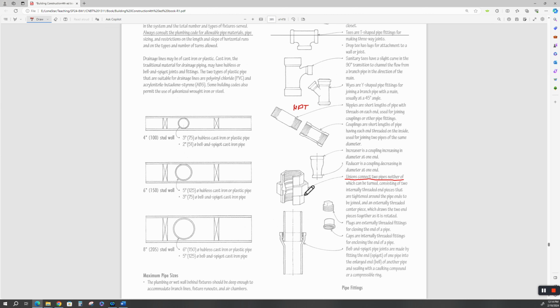Gas unions are a little different than a water union. Okay, gas unions will have an internal bolt in them. You lubricate that up good with plumber's grease and connect them. All right. And these are tightened on each end. You pull the pipes apart. They drop in. This collar then threads up and clamps it tight.